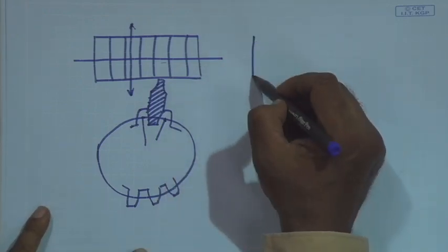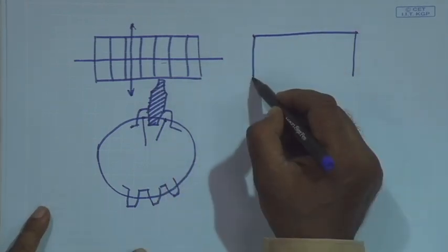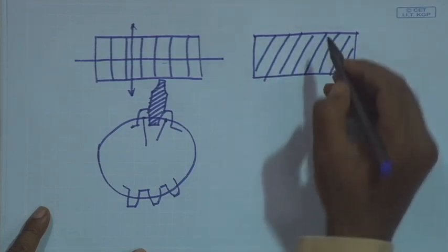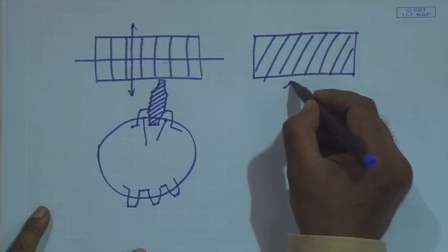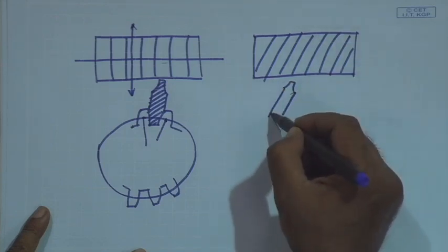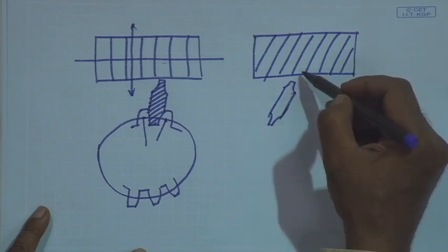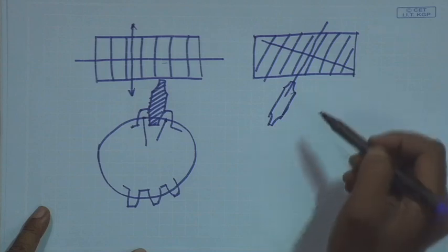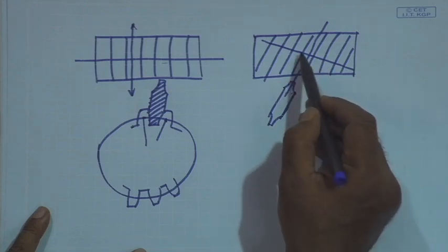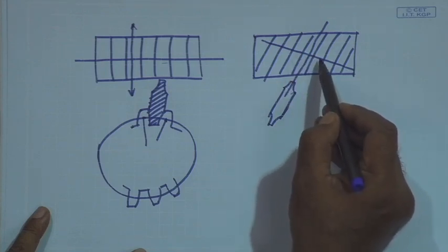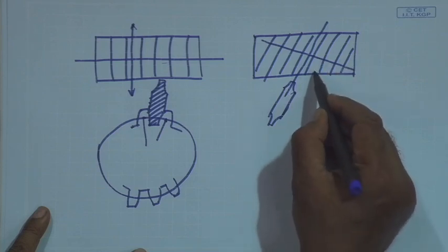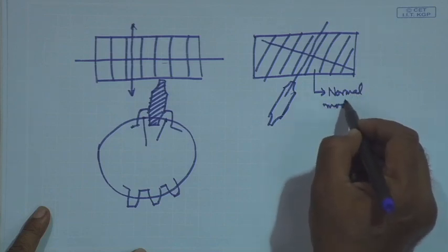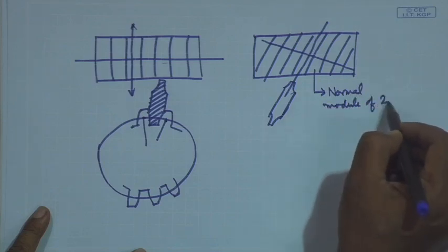However, if you are using the same cutter, in that case, if these be the teeth direction, the same cutter is used this way, and that information of the cutter is imprinted normal to the teeth. That means, normal to the teeth, the distance will be pi m from this point to this point. So, that is why we say that this helical gear has a normal module of 2.